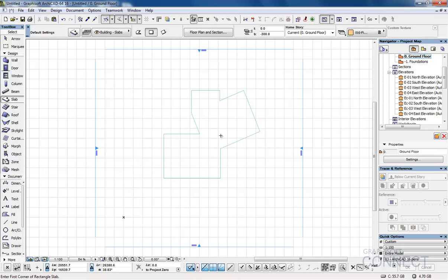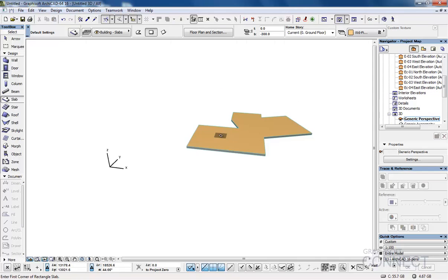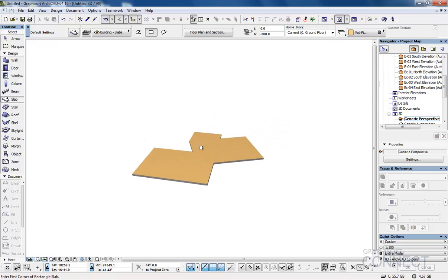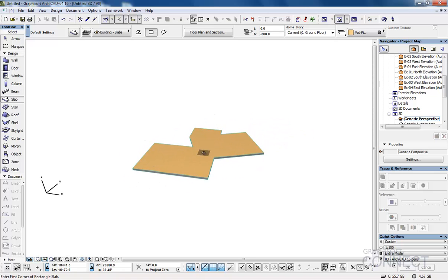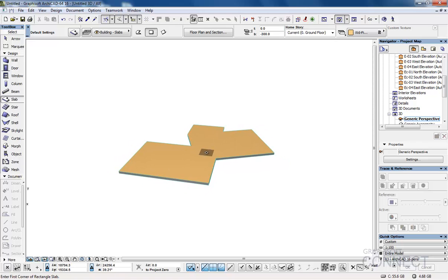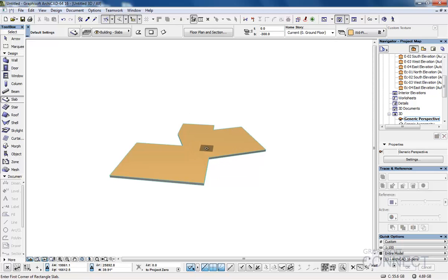So because it's Windows, I press F5, the 3D window appears and we can see the geometry. Like the 2D window, I can pan just by holding down the wheel of the mouse. I can zoom in or out by just rolling the mouse wheel, and I can double click and that does a fit in window. Zoom far away, double click, that fits to the window.